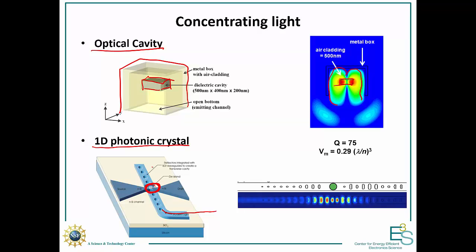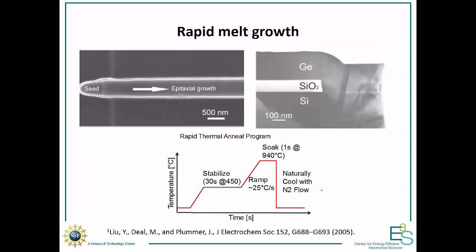So you could make that germanium photodetector quite small, and you can see a picture here of the idea. You've got the light entering here, and you have a cavity made in the waveguide. Photonic crystal cavity, and here's your little piece of germanium, and as you can see, the light intensity is strongest right in the center where your germanium is. So you're going to have a lot of absorption. So that's one path towards concentrating light and having smaller photodetectors with smaller capacitance.